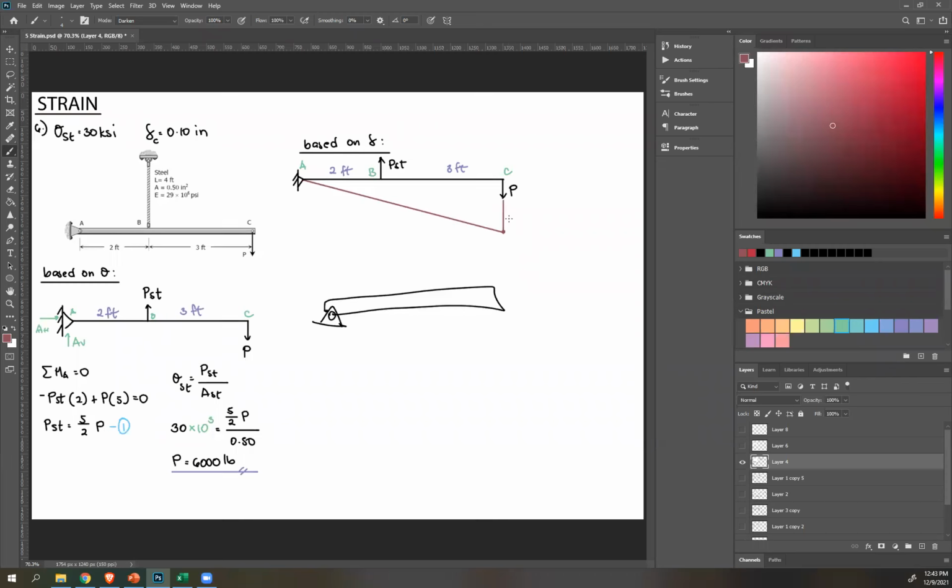And then that's the final position of this rod. You can say that this is how much point C displaced, and that's your delta C. And look here, at this point is attached to the steel rope. If its final position is this way, that means your steel elongated from this point to this point, right?